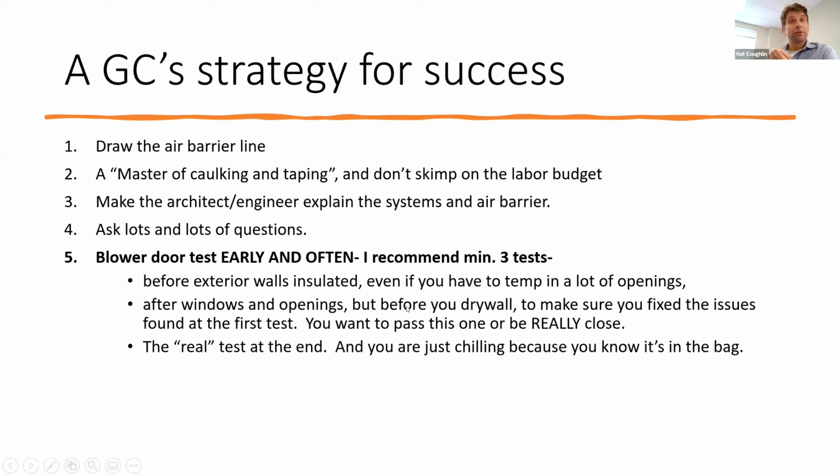And then a big lesson that we learned on the first job, and even the architect who'd done this a bunch said this was something he's going to start recommending. Usually people have said you want to do 2 tests, one before your finishes and one at the end. I was super paranoid about passing the blower door test. And so we actually did one before we'd insulated any walls, before we'd even received our doors and some of our windows. We taped in a ton of openings so that we could do a test just against the zip wall system and the connections at the foundation and the roof.